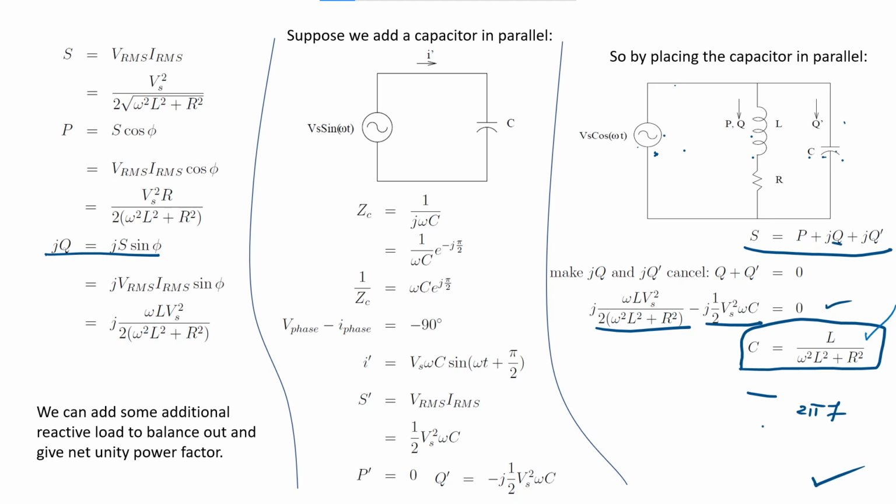In actual practice, when you see the power factor drop, you change the capacitor bank to another value. You may manually change the value, but you can also build a sophisticated algorithm that adapts automatically, so it's online control. To design such a control system, you need to learn control theory in the next semester. Okay, that's all for today.